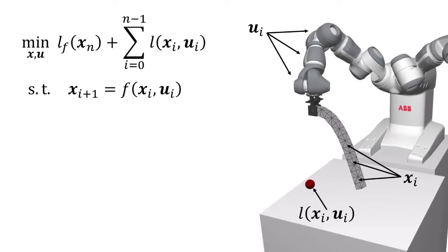Trajectory optimization problems typically appear in this form, where L and L_F are running and final costs, and F denotes an explicit transition function incorporating the system's dynamics. While this problem can be solved directly using a constrained optimization method, the drawback of this approach is that the candidate solution can only be considered physically correct once the constraints are satisfied. This is why we center our attention rather on single-shooting methods that leverage forward simulation. They bring the advantage of generating physically plausible solutions at each iteration.